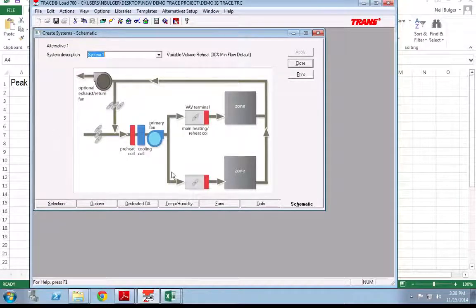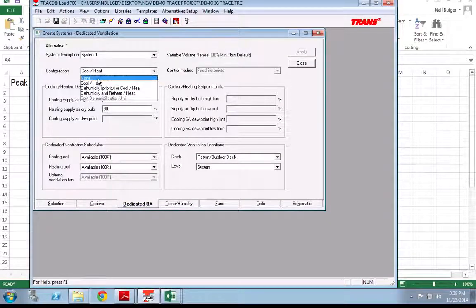And if that was not what we wanted to do, and we really wanted this pathway to be 100% fresh air and not have two cooling coils, and we essentially just wanted this damper to be shut, we would do that a different way. I would actually recommend not doing anything here. I would change this to none.